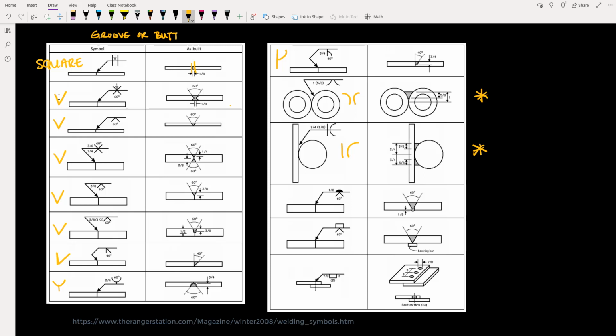So the welder would come in and simply apply a small tack weld to the side of this backing bar, and then they would fill in the weld here. And the backing bar would prevent the larger weld from dripping through the elements. And the same goes for this small bead weld above. That bead would be applied first, and then the larger weld would be filled in after.